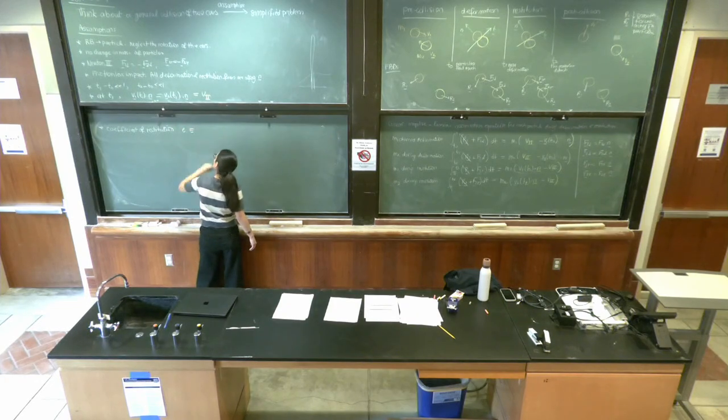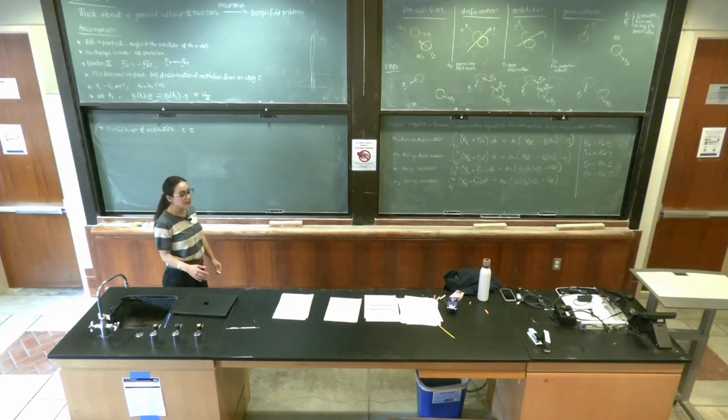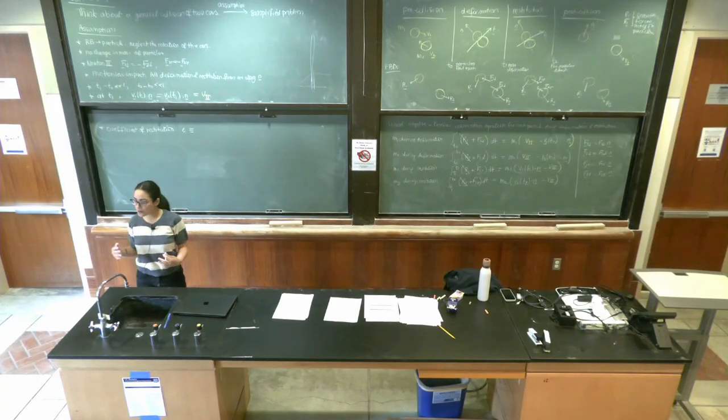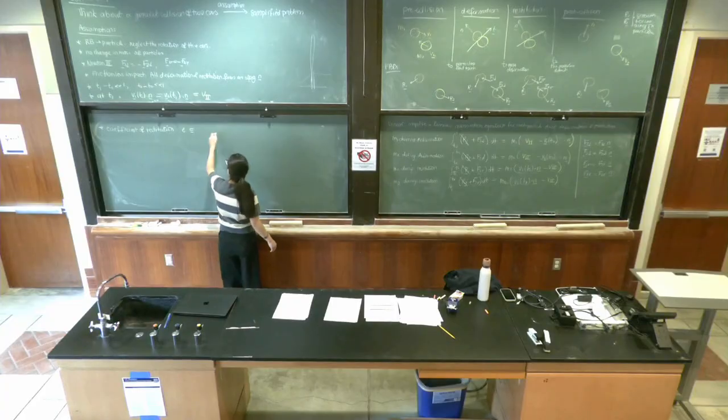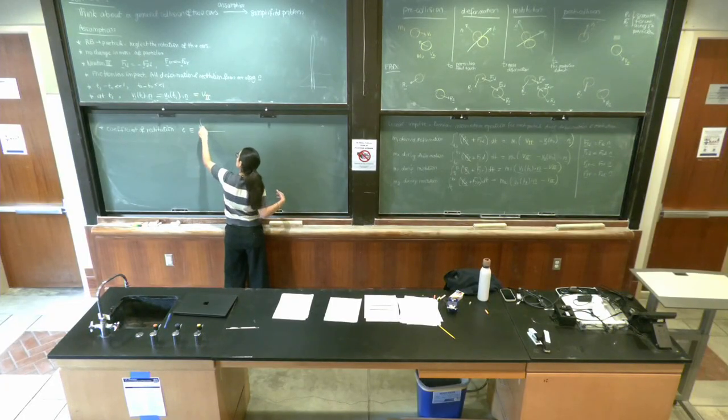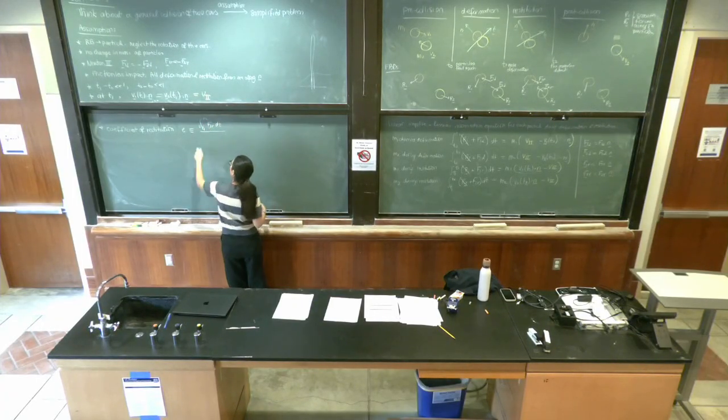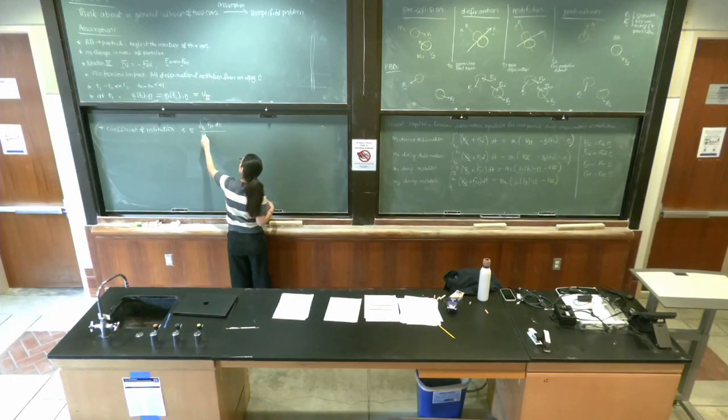E, which is by definition going to be the ratio of the restitution impulse over the deformation impulse for a particle. So that's equal to the impulse of the restitution, T1 to T2 of F1r dt along n, over T0 to T1 of F1d dt.